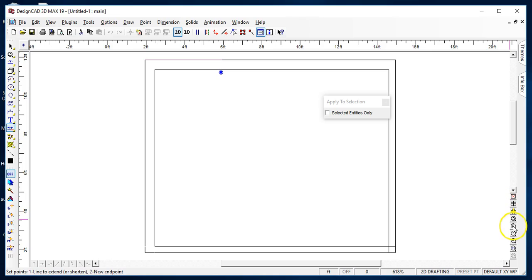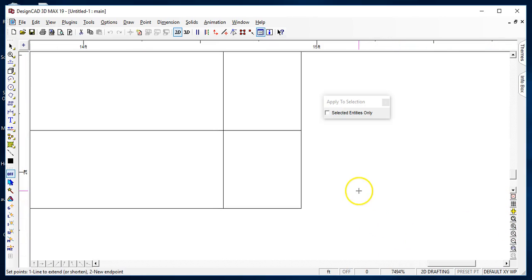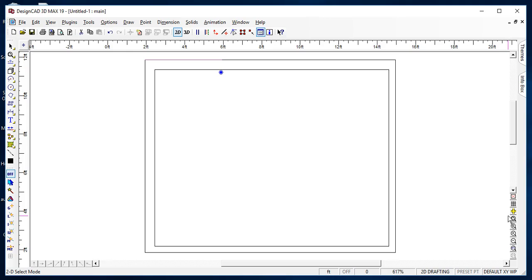Okay, I'll zoom into this corner to help clarify it. So right click or snap, and I'm going to snap to this point here, and you can see the line getting shorter. I lost the tool. Go back and get the tool. Right click and right click. Fit to screen. There we have it. Our perimeter walls with nice, neat corners.